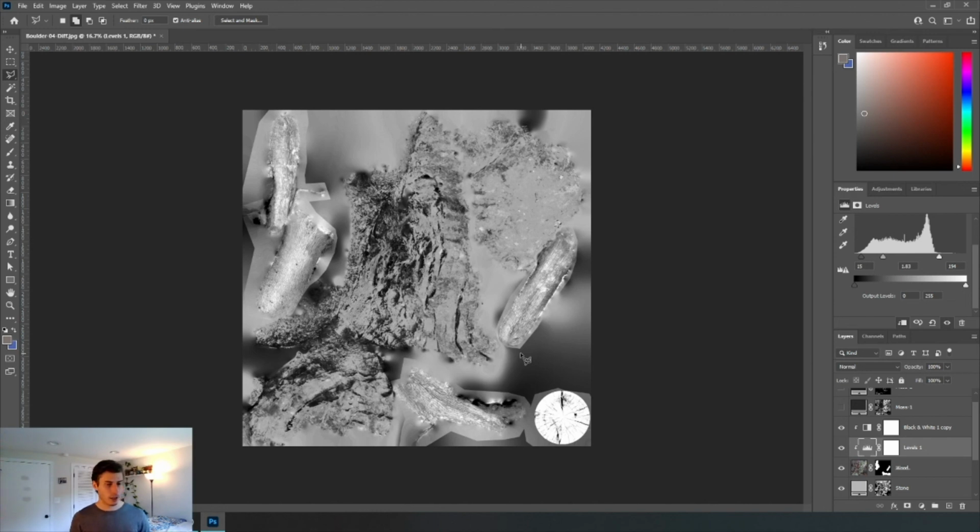And now we know how to delight our textures that we create. We know how to create a specular map, and then we also, from before, learned how to take a bunch of photographs of an object, upload them into a photogrammetry software, and create geometry and texture from that software to end up with some photorealistic assets. And I think this is as far as I'm going to go for today.